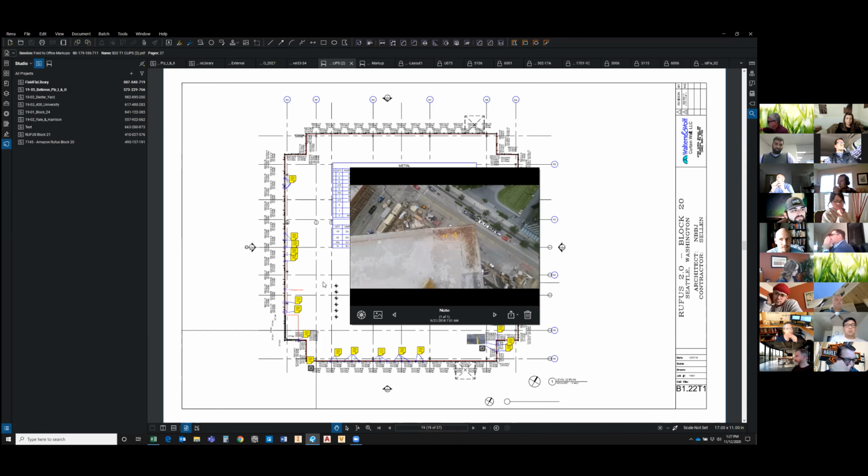Because if it's a field fix that's already been taken, we try to make our field fixes as general as possible. So if the slab is in 1 inch, we're going to try to find 1 inch beyond tolerance. We're going to try to make that field fix work for the whole building. And that way, we don't have to recalculate at every specific position, right?